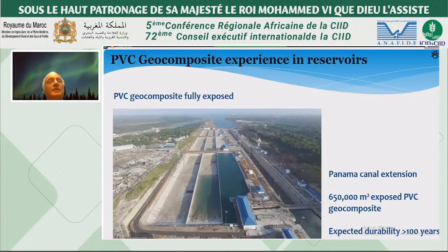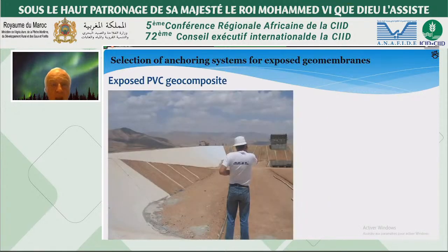As mentioned by Professor Giroud, they have been used also for big reservoirs, like for the Panama Canal extension, where 650,000 square meters of geomembrane, of geocomposite, have been installed instead of concrete, with an expected durability exceeding 100 years.